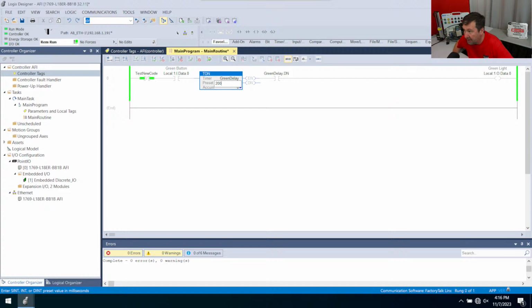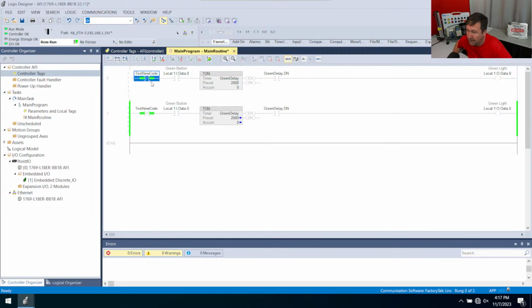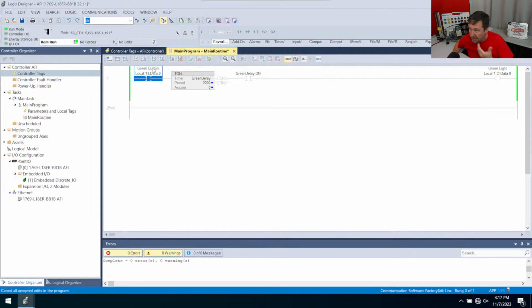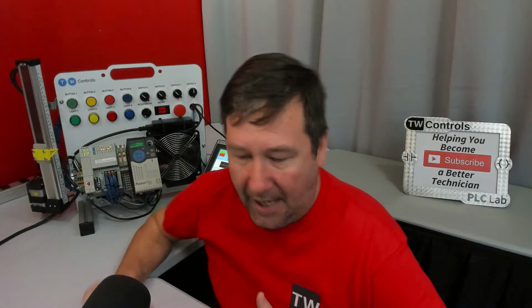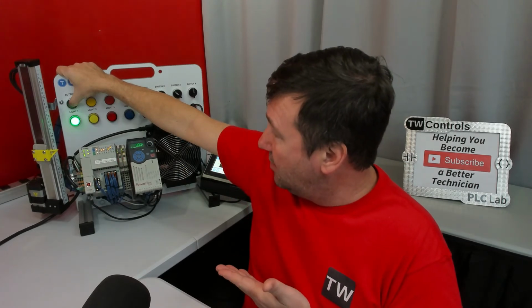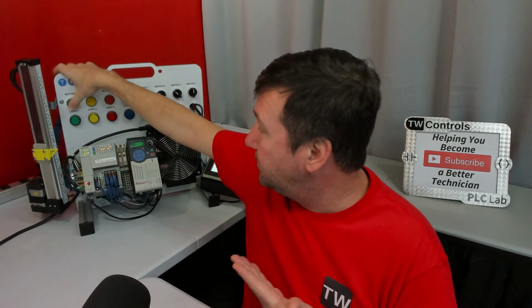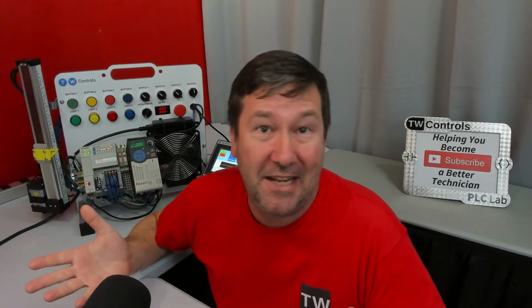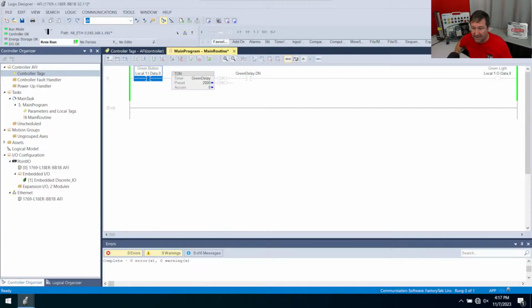So I'm going to put a 2000 millisecond delay. And now, whoops, just for realistic, I need to take that back out. That way we're back like we'd never had this issue. And now when I press the green button, 2 seconds later, the green light comes on. Okay, now we want to make the same edit. We want to make it where the yellow light does it.